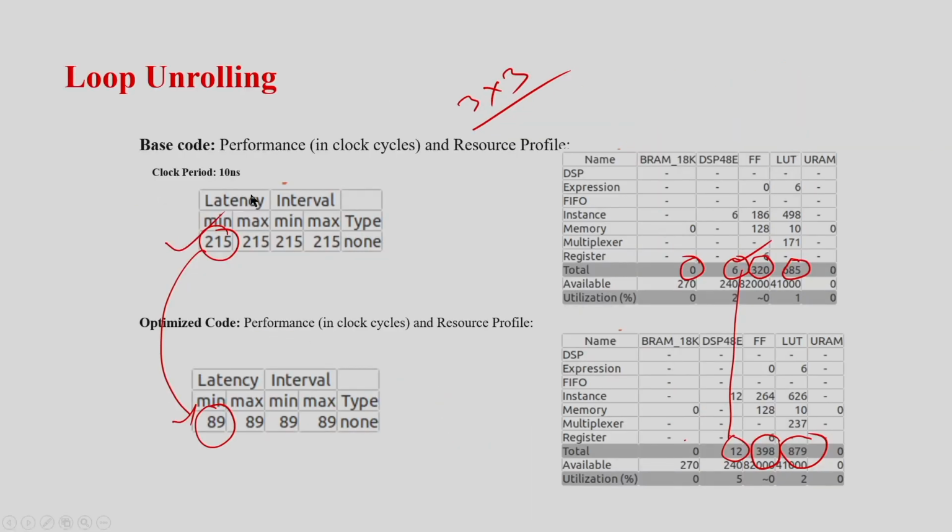So, that is why even in the rolled implementation, although there is only a single multiplication in each iteration, it is still 6. This might vary for the target architecture, because if I take a different FPGA board, the DSP configuration may be different, right, and based on the DSP configuration the number of multipliers will be decided. Here I probably took a very small board, so that is why it shows more than 6 multipliers, but I hope you understand the overall idea here.